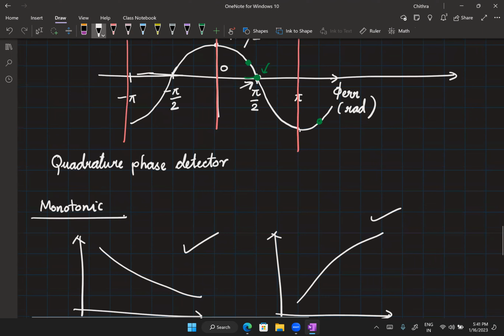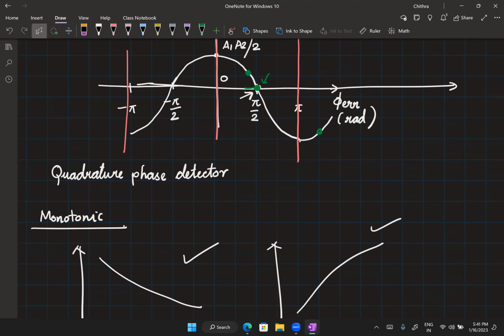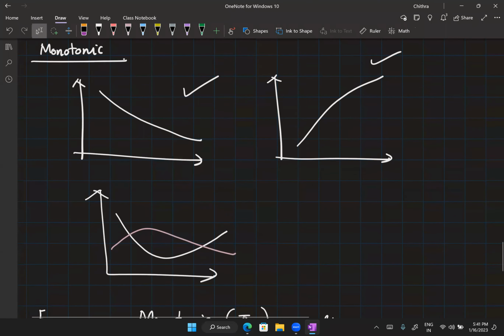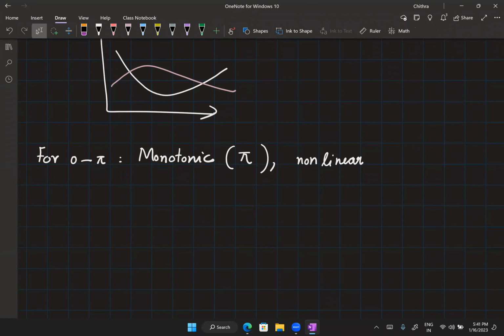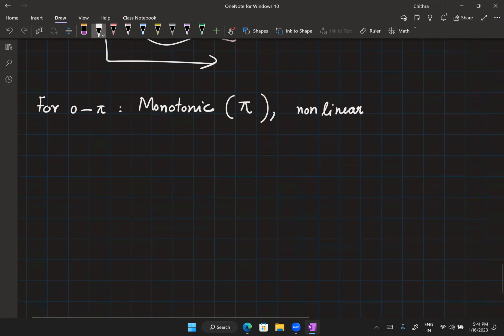We'll just do small signal analysis and linearize it around a particular bias point. That's it. Okay. So now we have to define a gain for the phase detector, right? So this gain, again, represented using KPD, is defined as follows. You look at by how much your phase detector output is changing when you have an incremental change at the input.